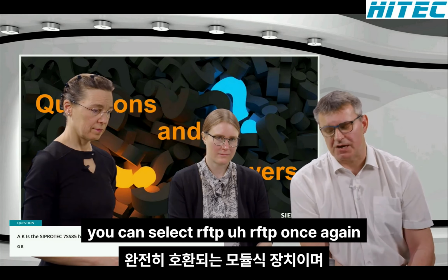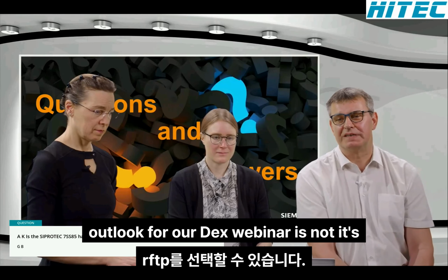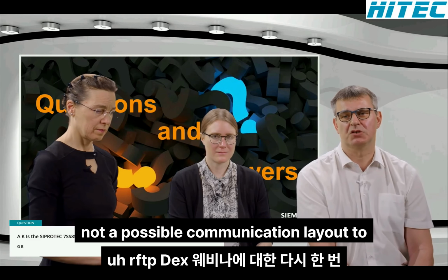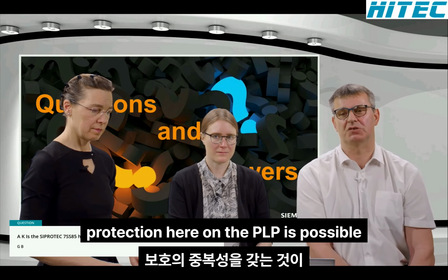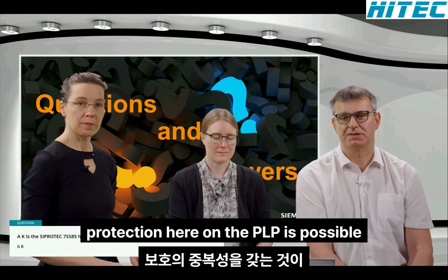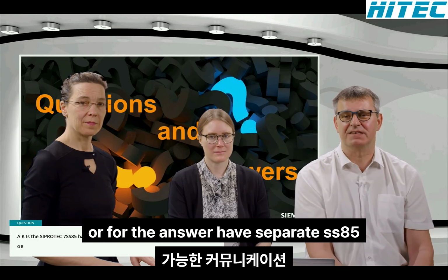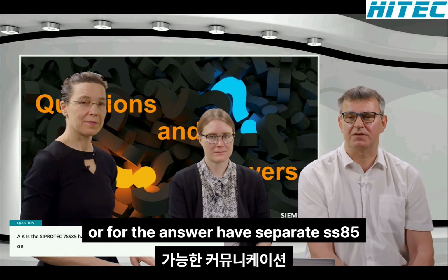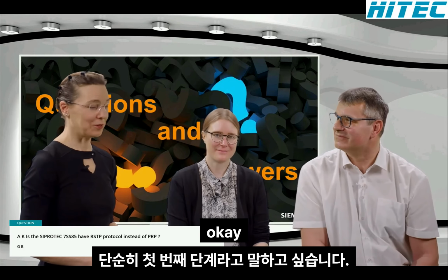But RSTP, once again, outlook for our next webinar, is not a possible communication layout to have redundancy of the busbar protection. Here only PRP is possible. So for the answer, does the 7SS85 have RSTP protocol instead of PRP, I would simply say in the first step, no. Okay. No.